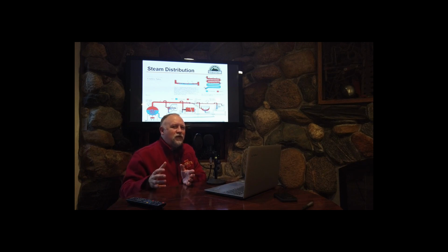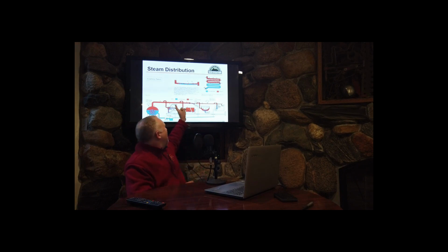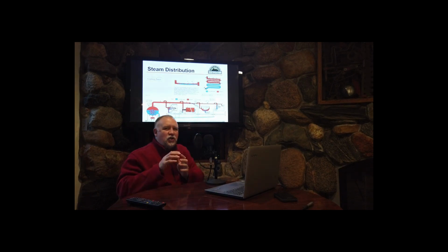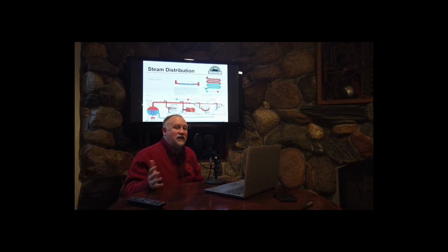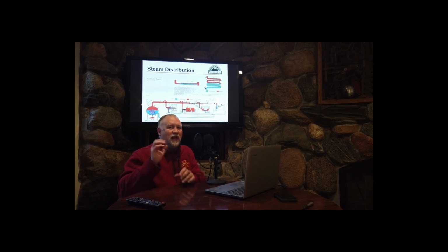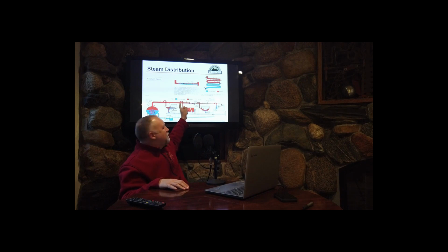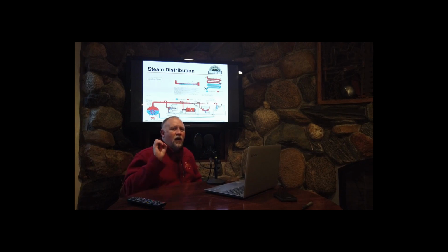Well, what happens to the specific volume as you go from water to steam? It expands greatly. And what will happen is the pressure in this pipe will actually surge, almost like a steam engine. Steam engines do this. They puff, they surge, they build up pressure and use it, and build up pressure and use it. Well, if that same thing happens in this pipe, it will cause pressure spikes.